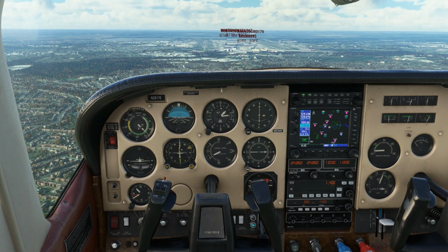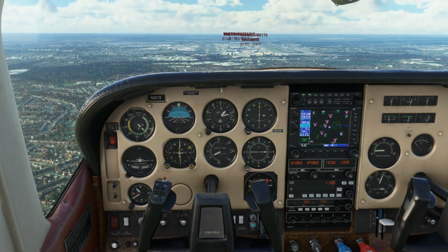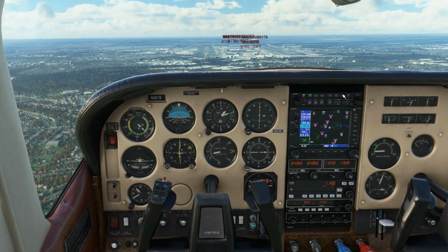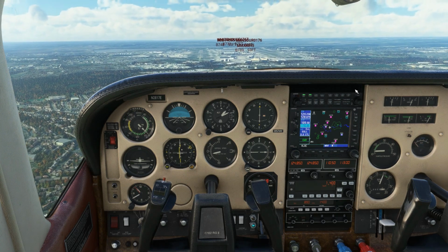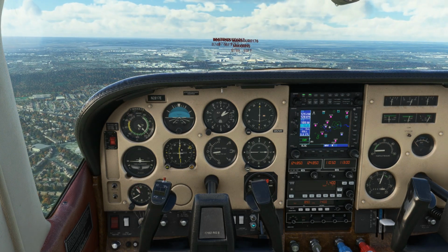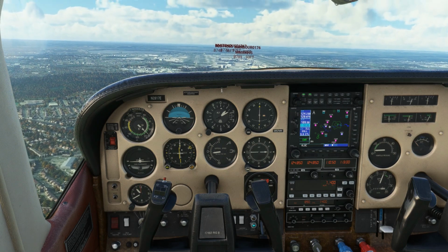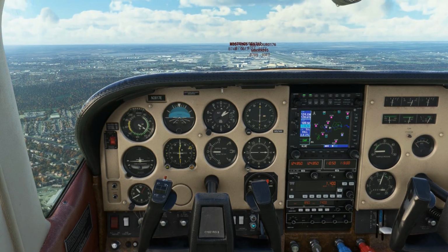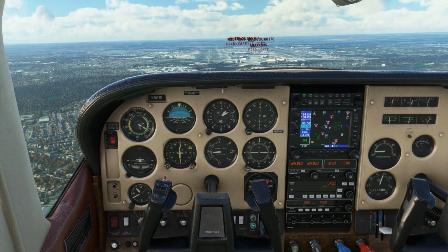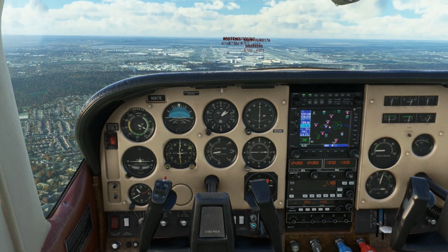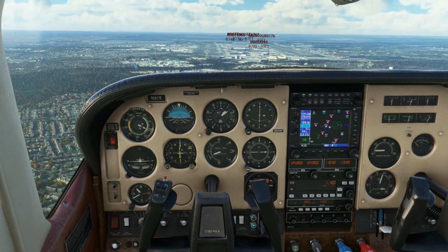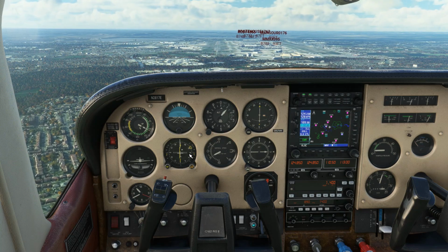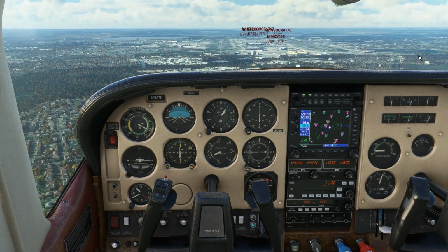So there we go. Now I've slowed down, so I'm just going to pull back on my yoke to keep those indicators in the centre where they are at the moment. Keeping an eye on my instruments. I'm going to go to another stage of flaps. The aircraft will want to flare, but it will start to want to nose down after. Keeping the indicators, I need to descend slowly to get those indicators back into the centre. These two yellow indicators.